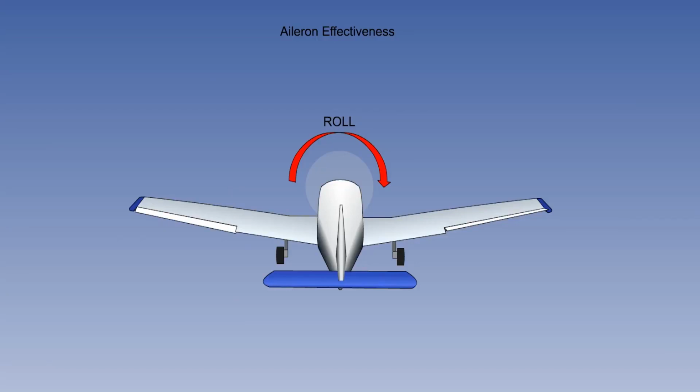At low air speeds, and therefore low dynamic pressures, the effectiveness of all flying controls for a given displacement is reduced. This effect on the rudder has already been mentioned, but the ailerons are similarly affected, of course. To obtain the required response, greater deflection must be used at low speed.